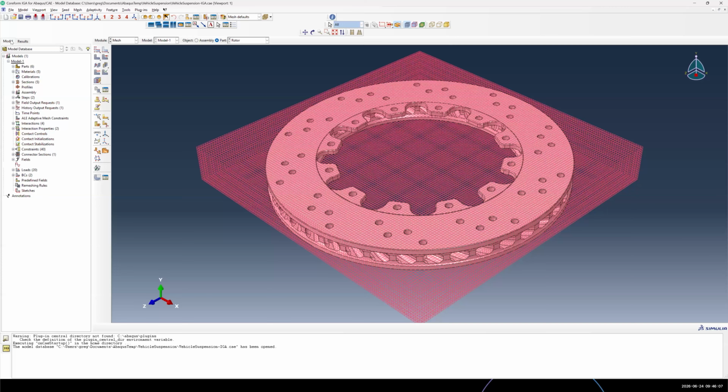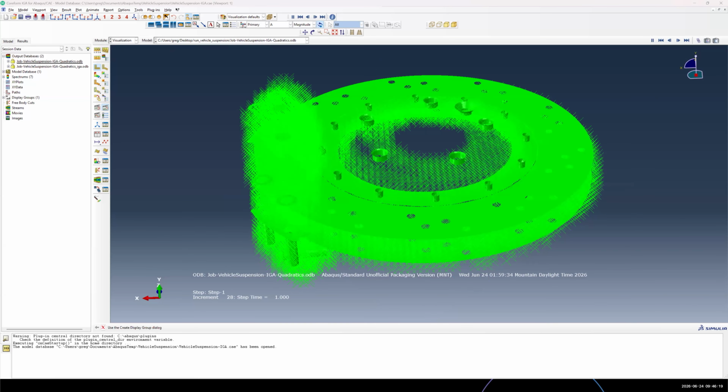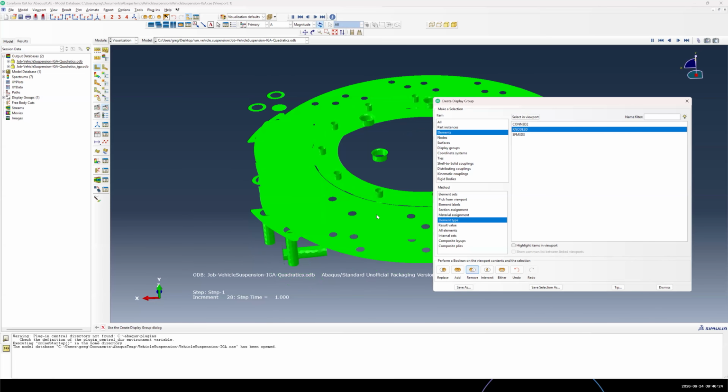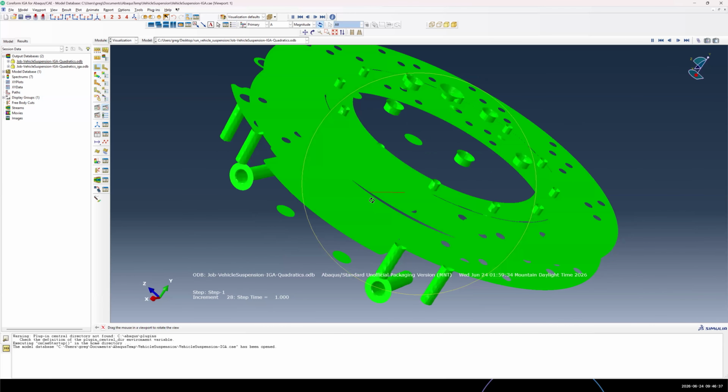We do create this input deck that then produces these surface meshes that I mentioned. Just to show these again, you go over to the visualization module. Again, the X's here are the default rendering of user elements in Abaqus, and those are these R3D nodes. If I remove those, you'll see that what we're left with are my connector elements and these surface membrane elements. You'll find those surface membrane elements in the INP file that we star include. So if you need to do some micro adjustment of those, you certainly can.